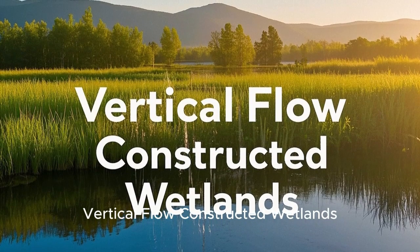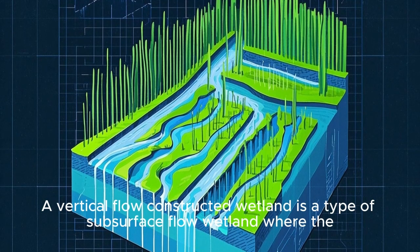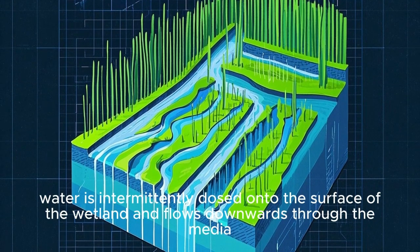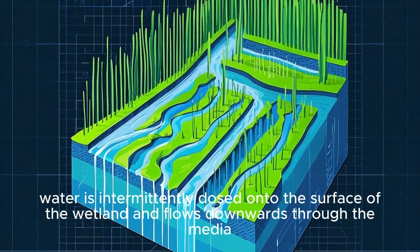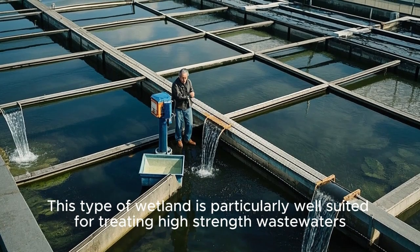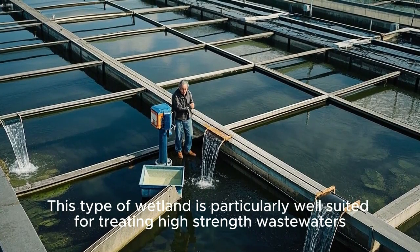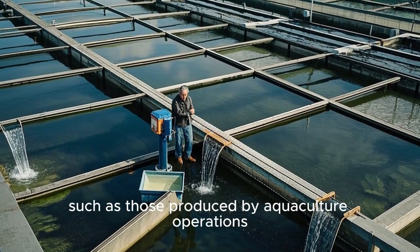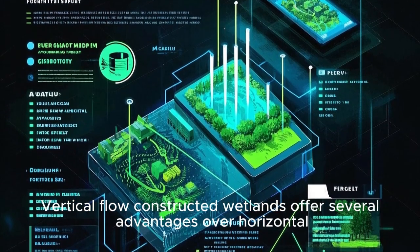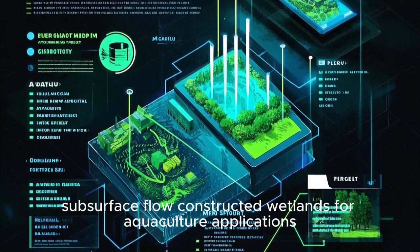Vertical flow constructed wetlands. A vertical flow constructed wetland is a type of subsurface flow wetland, where the water is intermittently dosed onto the surface of the wetland and flows downwards through the media. This type of wetland is particularly well suited for treating high-strength wastewaters such as those produced by aquaculture operations. Vertical flow constructed wetlands offer several advantages over horizontal subsurface flow constructed wetlands for aquaculture applications.